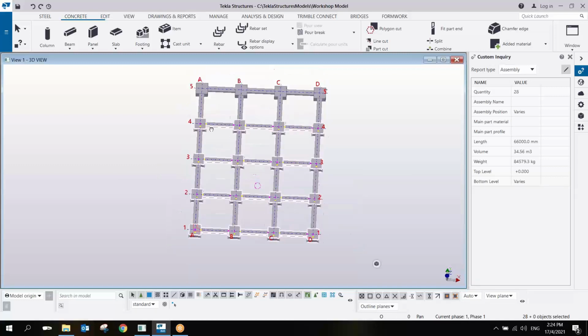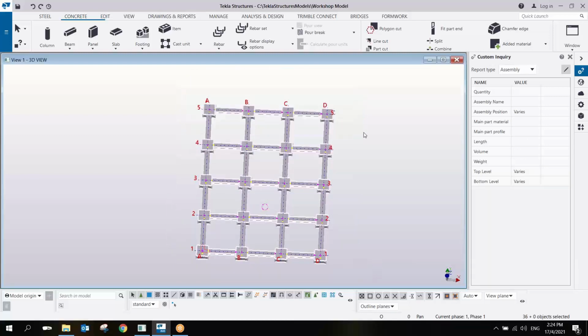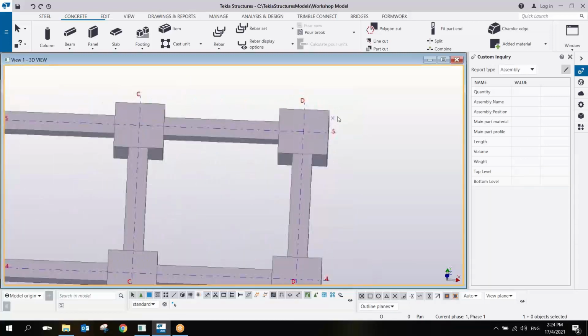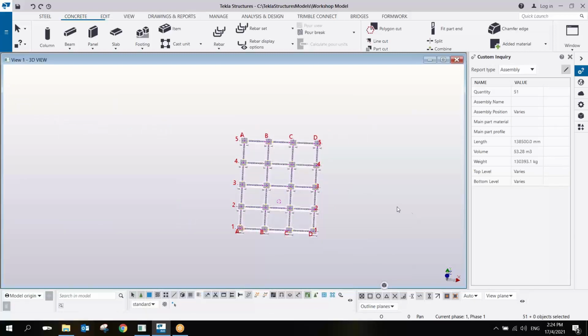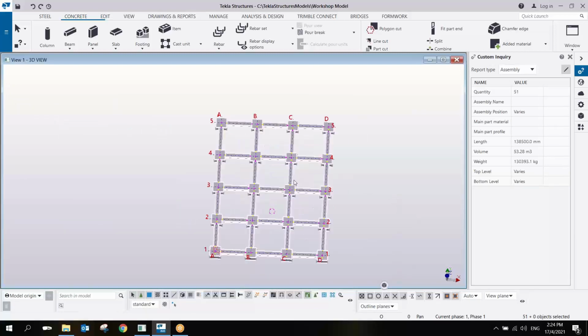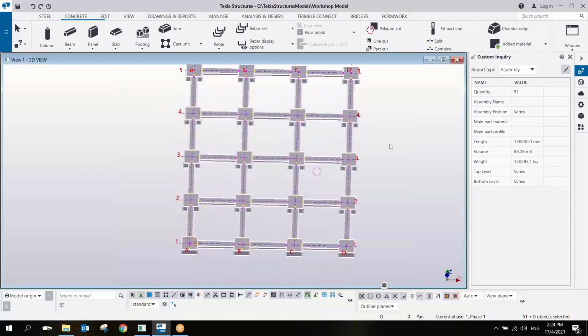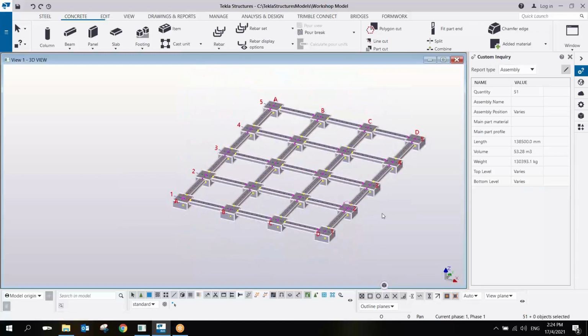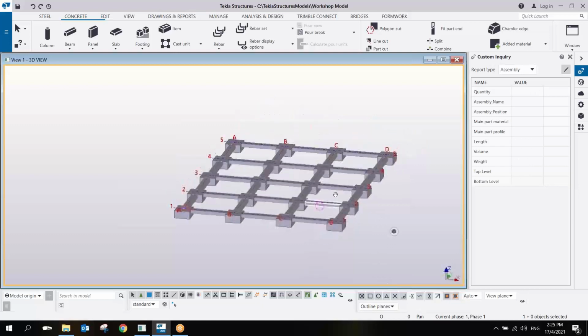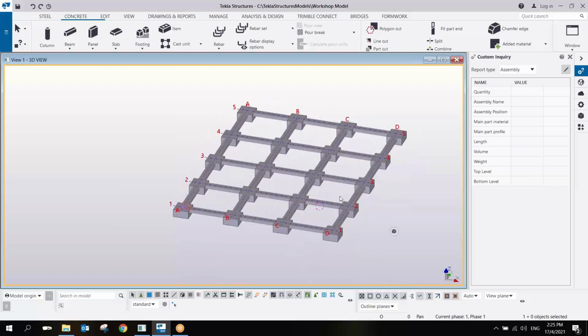All right, as you can see here, there is a point there that I'm selecting. Yeah. So you need to select only the element so that it will give you the total volume of 53 cubic meter. For your reporting, you can easily get that one. No need for you to calculate.